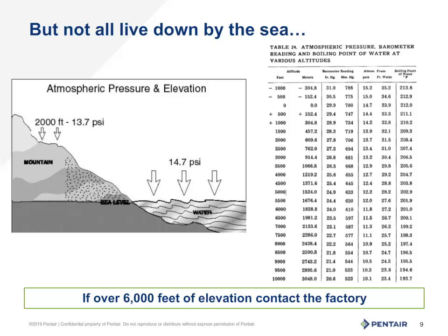But what about elevation, you ask? That's a great question. Yes, that does make a difference. You lose 1 psi for every 2,000 feet you go up in elevation, up to around the 6,000 foot mark. If you're going beyond that, you can find a chart as it's shown here, or give the factory a call and we'll be glad to assist you.